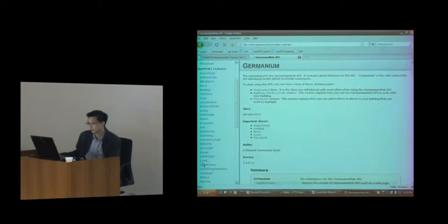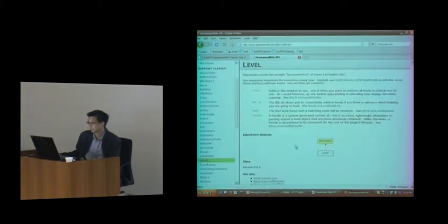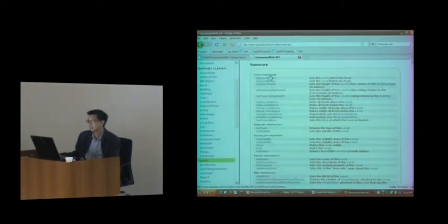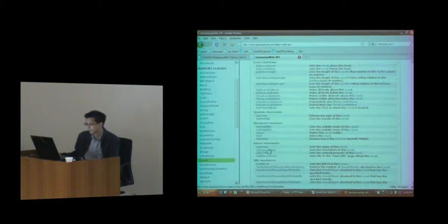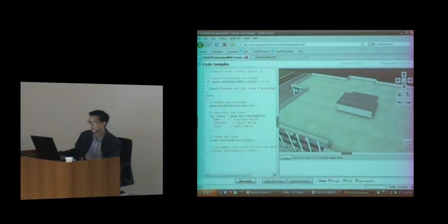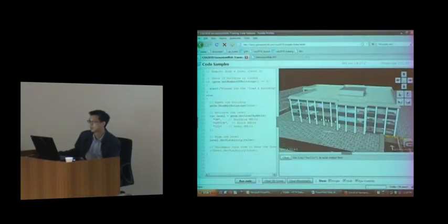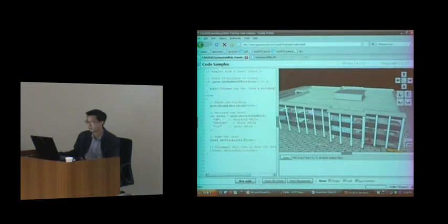So in this case, if I go look at level, yeah, I can traverse the levels, I can get their names, the descriptions, and I can show and hide them. Okay, so in this case, what we want to do is just to hide it, just to make sure that we actually have retrieved the correct level. So we just set visibility false, or to make it easier, let me just call hide.